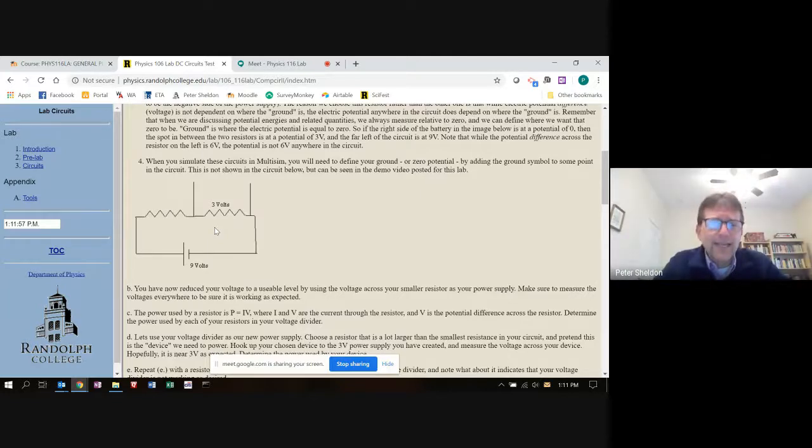Yeah, it's 2 to 1. Like a 1,000 and a 500, probably. Exactly. And you could figure out that therefore it's going to be 3 volts across the 500, because if you did 1,000 and 500, then you'd have 1,500 total in series.